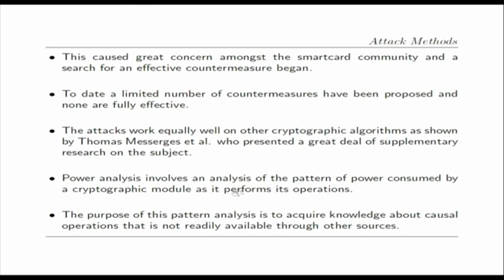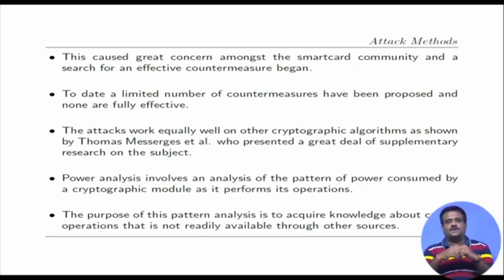So, power analysis involves an analysis of the pattern of the power consumed by the cryptographic module as it performs its operation. Suppose we are running an encryption scheme in hardware. Power analysis will just analyze the power consumption while it is implemented in hardware. That is the observation we have to make: how much power consumption, how much power fluctuation. So, we have to have a machine to detect that.